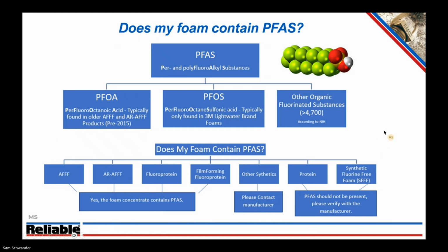Okay, so to ask, does my foam contain PFAS? So any of those carbon-fluorine bond materials. So an AFFF, like I said, AFFF, fluoroprotein, film-forming fluoroprotein, yes, that material is going to have PFAS in it. You'd want to talk to the manufacturer on if it contains PFOA or PFOS, but as for the genre of chemicals, it's going to have PFAS.